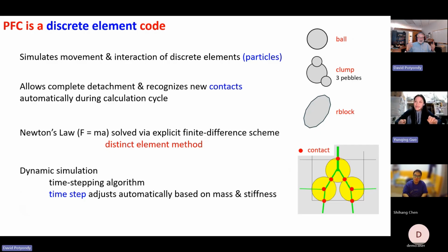Because it's a time stepping thing, that means there's a time step. If you have a really crude code, the user just has to select a time step, and you just have to use that all the time. It turns out, based on the mathematics of the finite difference equation that we wrote, you cannot make that time step infinitely big.